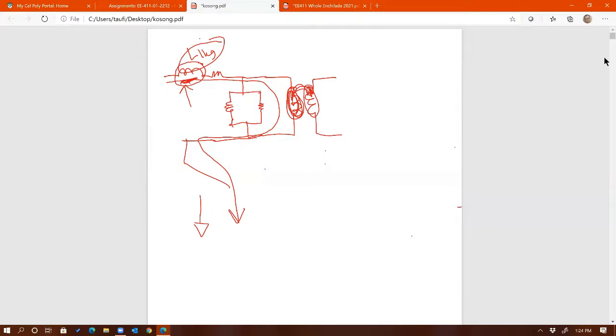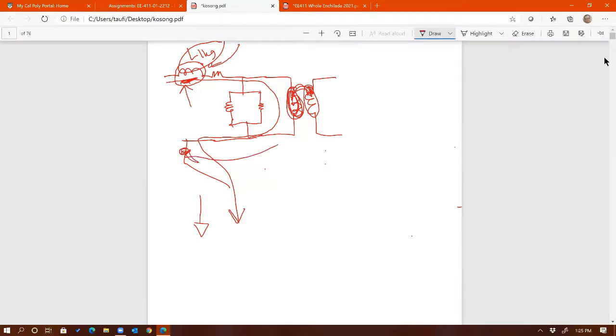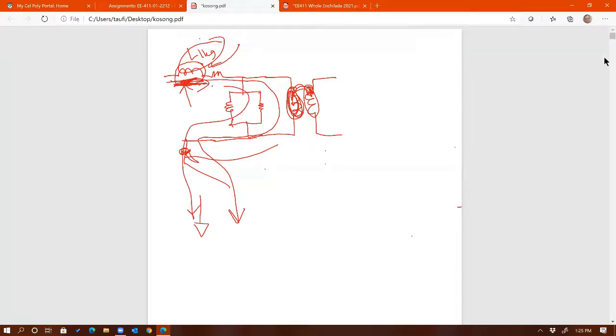So remember from EE411, inductor current cannot be stopped, right? Same thing here. If you stop the current here, then this inductor gets upset, and how do we know that it got upset? Well, you can see it from this voltage right there. As you are turning off that switch, this inductor refuses to stop. Its current has to flow still. So how does it try to make sure that this current keeps flowing?